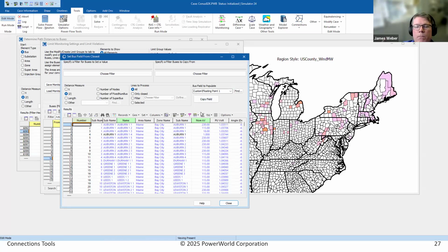So one example calculation I have seen done, ERCOT is putting out full topology cases now, but it's not completely full topology. Many of the generators in the case, I suspect they're future generators, so they don't really have a sub yet, are put in the case and they don't have a substation assigned to them. And maybe you're like, you know what, I just want everything in the case that doesn't have a sub to get assigned to the substation of the bus that it's closest to.